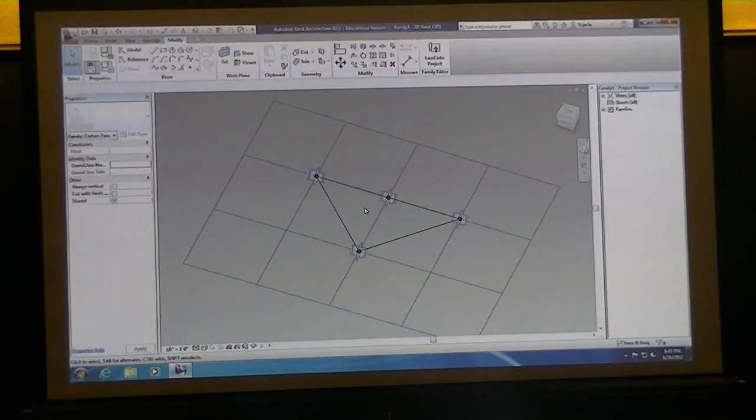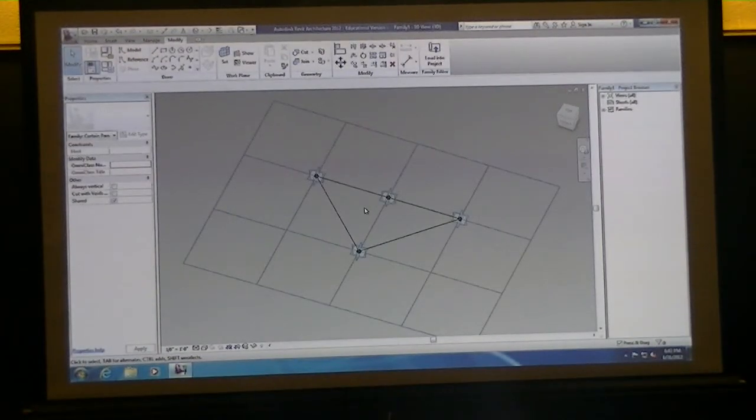So if you're trying to have a certain density of your shape, when you start to use curtain panels that stretch over multiple grids, you may have to divide up your surface even more so that you can get a smaller scale, because this will actually be taking up two squares instead of just one. But you can also see you get an extra point on this particular one because it's a triangle bent. And again, these are your different adaptive points that are going to snap to the underlying grid on a divided surface.